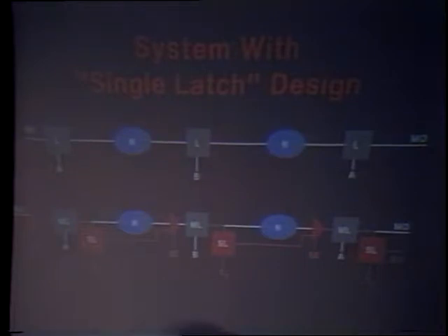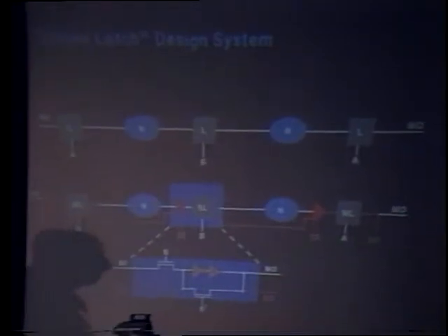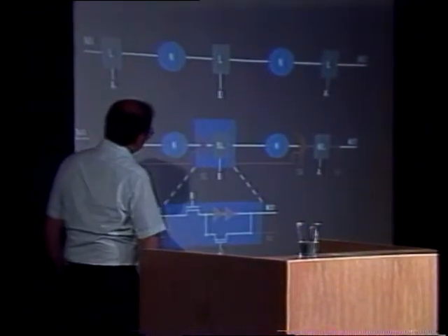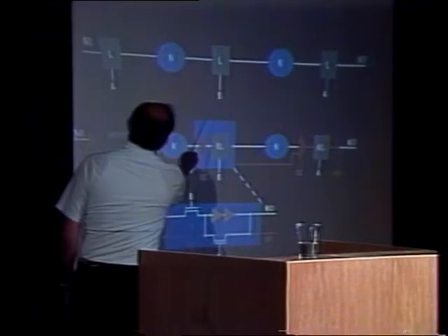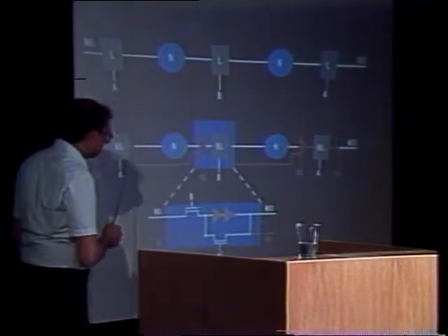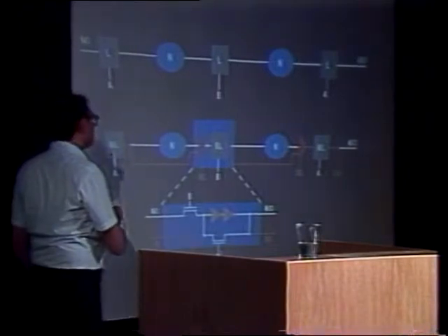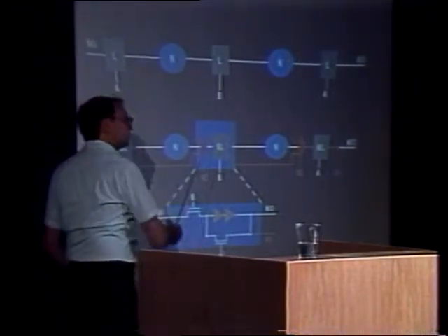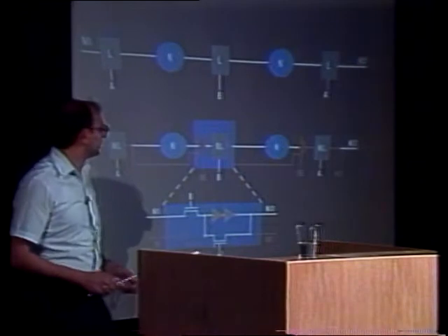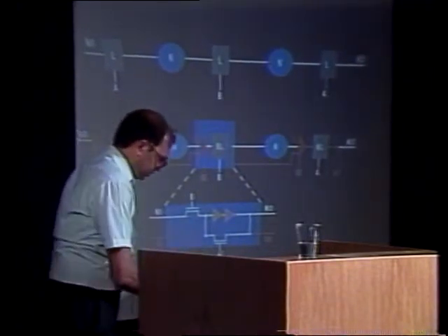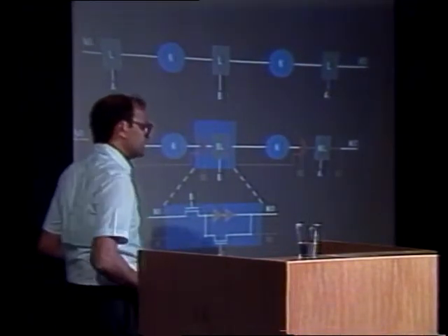I agree, okay? If that is the case, you may wonder why not implement scan design as shown here. If we have two latches clocked by different clock phases, A and B, why don't we, during test operation, operate this one as a master latch and this one as a slave latch? That would work perfectly all right, except that this picture is deceiving.